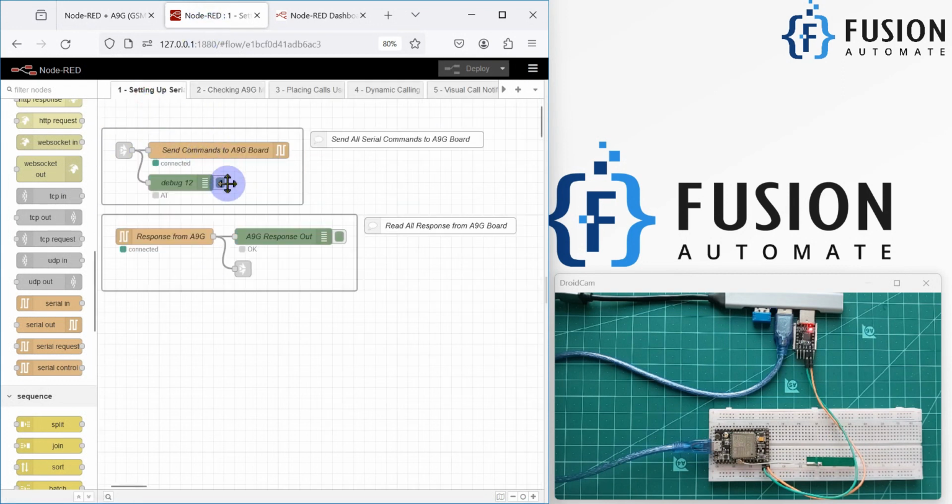The two main nodes for the entire series are the serial out node and the serial in node. Whatever AT command we want to send, we can send using the serial out node, and whatever response we want to read, we read using the serial in node.